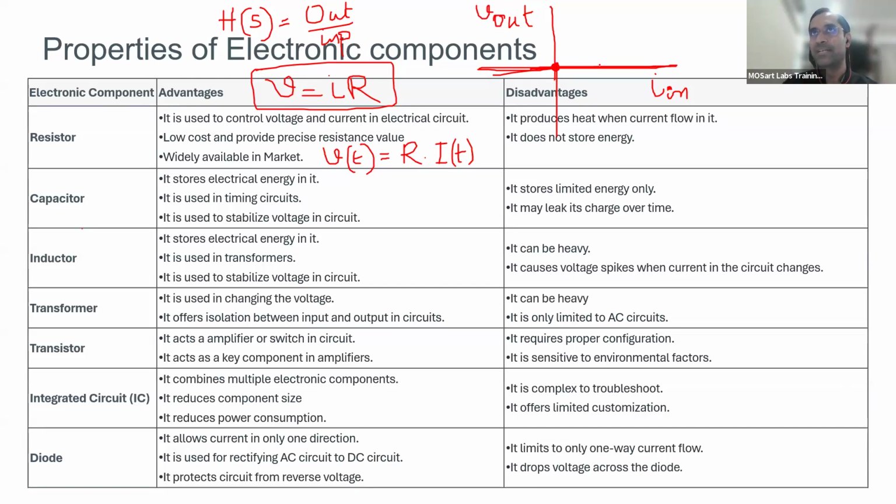When you have some current, let's say you have 1 milliampere as an example, then you will have some corresponding voltage here. You have twice the input, you will have twice the output, right? So now which other points you have? You've got this point, you have another point here, and so on. So this is my transfer characteristics. Do you agree? Slope of this line obviously is the resistor, right?